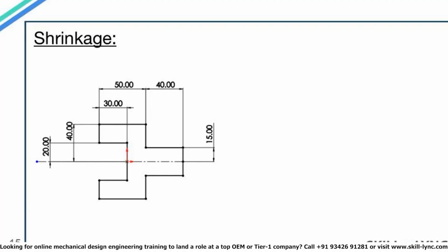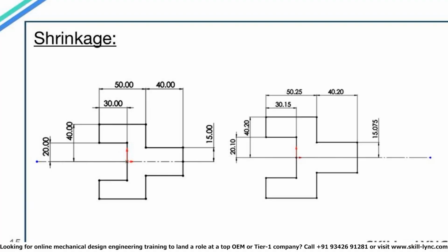Now, if you create mold blocks for the same dimension as shown in the figure, then once the molten plastic material gets solidified, the component will shrink and the final part which you obtain will be even lesser in size compared to what you see in the diagram. In order to avoid this problem, we always create a mold for a model size bigger than what is actually desired, as you can see in the image. Now, you might wonder how we will know the exact increment in size of the mold to account for the shrinkage.